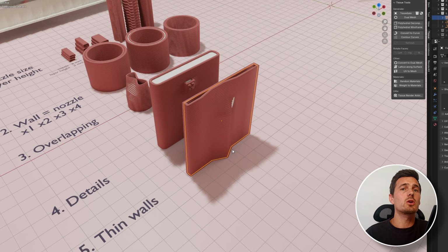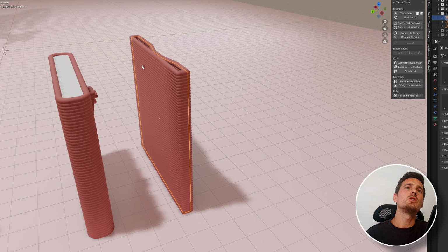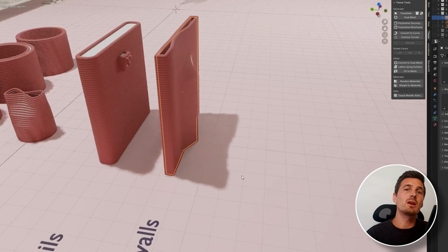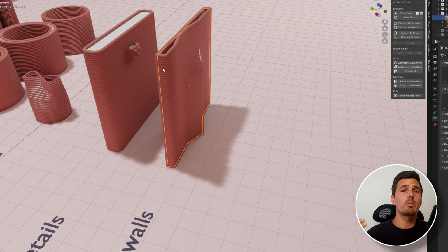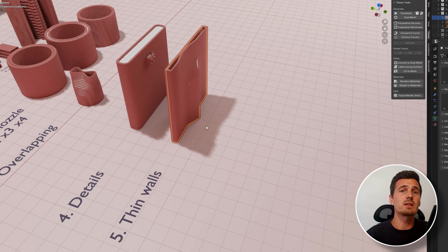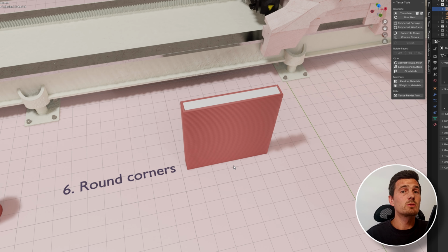So also in this case, ask your manufacturer what the right settings are for long thin walls if you really need it. If you are, for example, designing a table, you want to have one flat long part, but that doesn't mean that on the other side of your part you can't include some ribs or some curvature. This makes it way more stable and less prone to deformation. Which brings me to number 6.